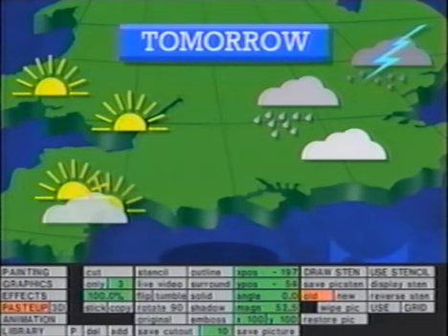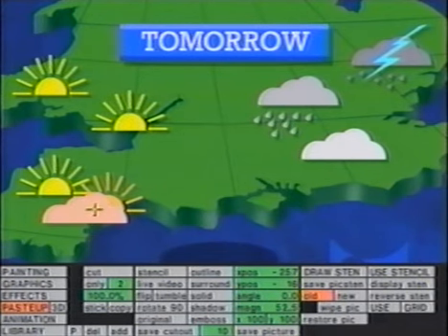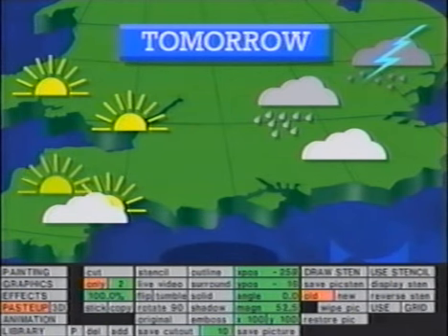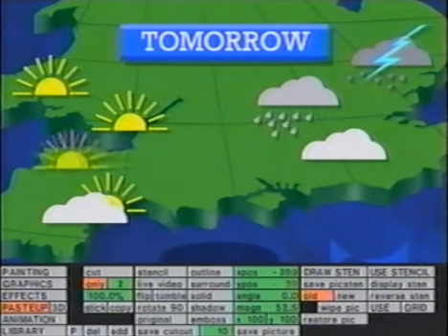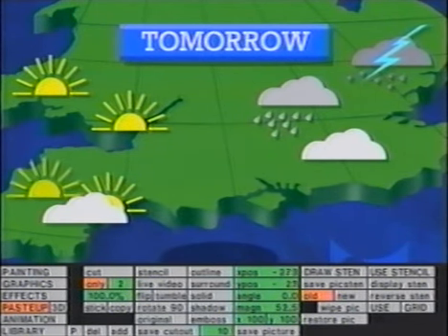Finally, to ease selection of a cutout, Only ensures that a particular numbered cutout will be selected and moved. Without Only, it can be difficult not to pick up other cutouts when close to them. Only makes operation clearer in a crowded situation.